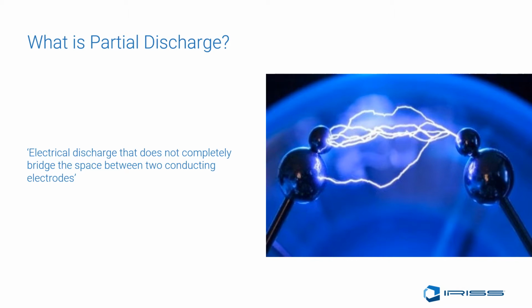Partial discharge may be found in liquid-filled transformers where the paper insulation starts to degrade with exposure to high heat levels. This will lead to oil losing its insulation value, and the degradation of cellulose paper becomes more rampant. This produces bubbles in the oil, which allows the conduction of current inside the equipment, which in turn will show as TEV and ultrasound indications. Partial discharge can even occur around the connections and insulators on transformer lines or in substations.